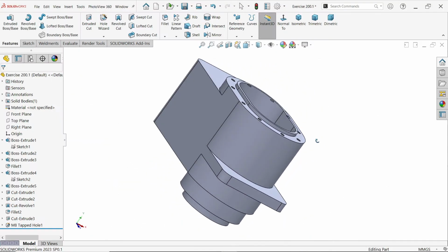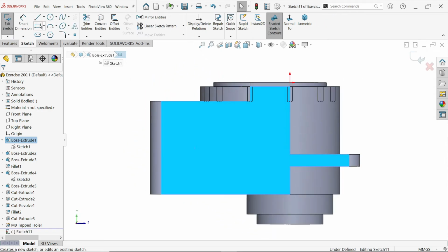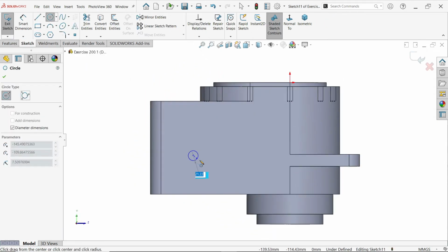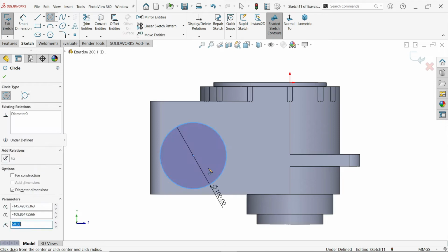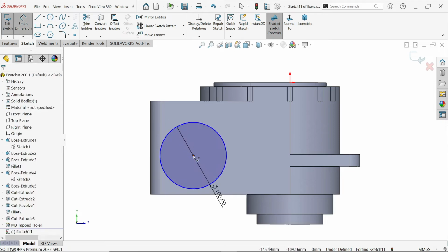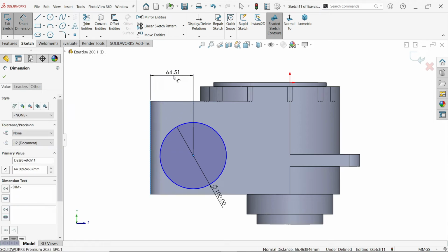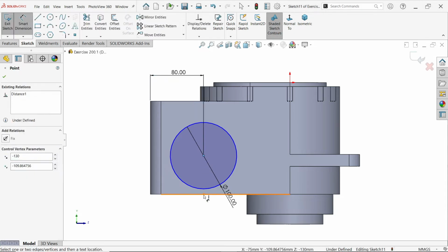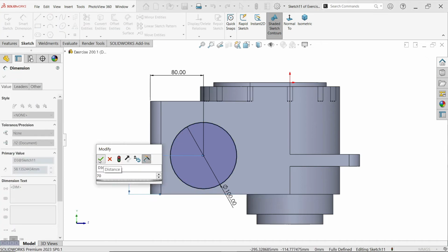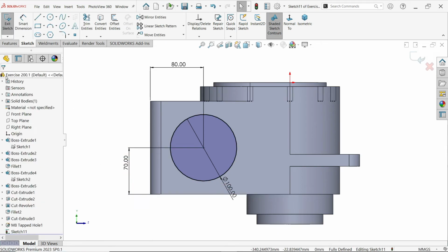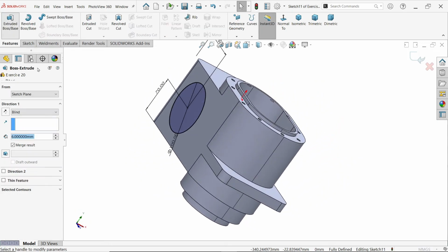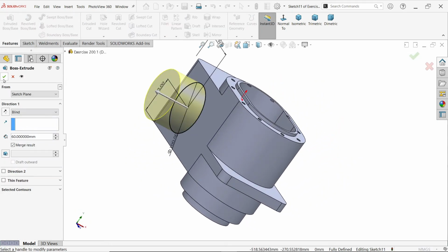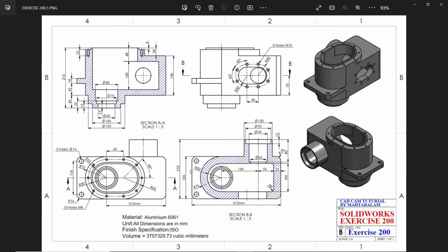Now select back surface, sketch, draw here 100 millimeter. Press escape key to get out. Now distance from here to this side, it's 25 plus 55. And enter. And distance from here to 70. Extrude 60 millimeter. Okay. Now you will see distance 150 minus 210 is going to be 60 millimeter.